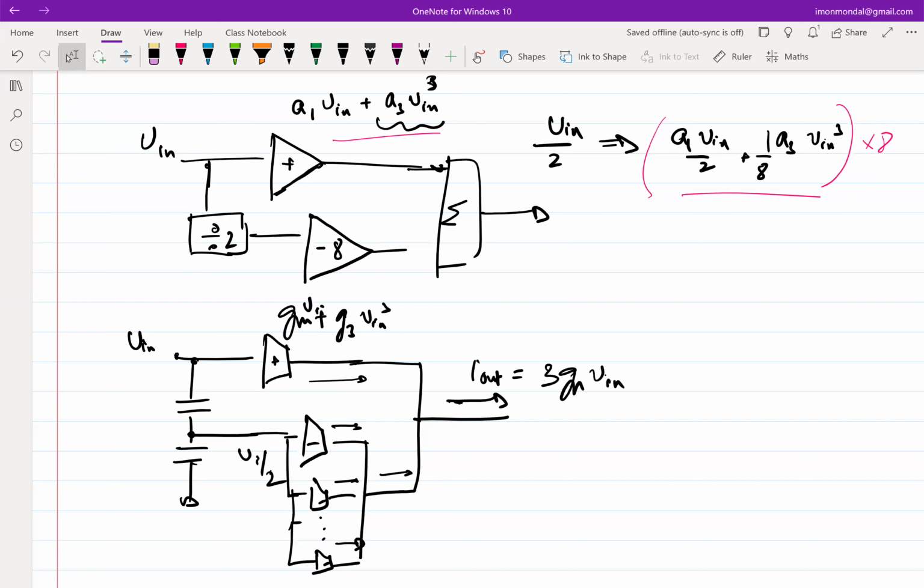In fact, it's going to amplify the fifth order. So if your signal swing is not limited so as to ensure that the fifth order nonlinearity is small enough, then the fifth order is going to kill you.